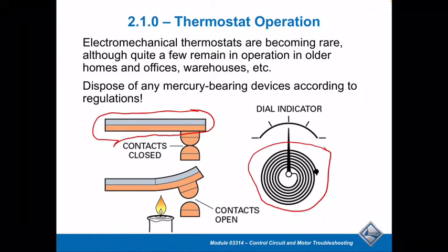All of those thermostats have some things that they need to do. One of them is they have to switch contacts. For example, I need this set of contacts to create a nice, quick, snap-acting contact closure to allow a heating system or a cooling system to function as you want it to.